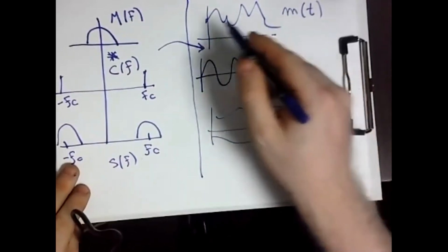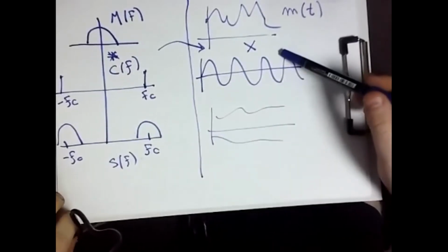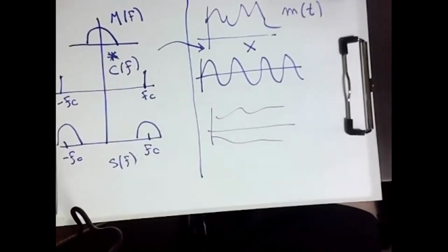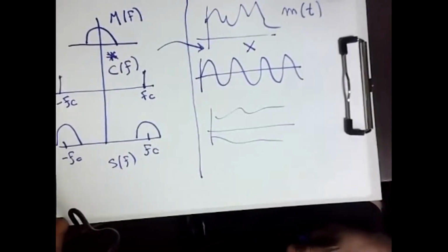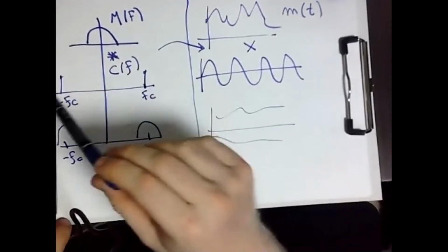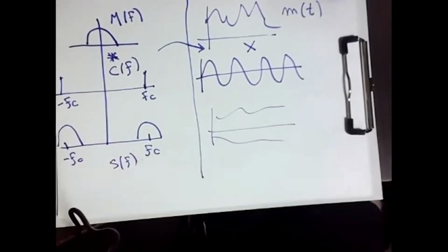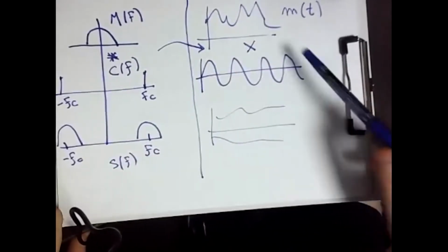So, what we have concluded from this example, my dear students, is that modulation is a convolution process in the frequency domain, so it's a multiplication process in the time domain. Carrier is a two-delta function in the frequency domain, so simply it's a sinusoidal signal in the time domain. Again, for those who have attended our first extra session, discreteness in the frequency domain causes periodicity in the time domain. Just a hint for the A+ students. And then we have this multiplication.